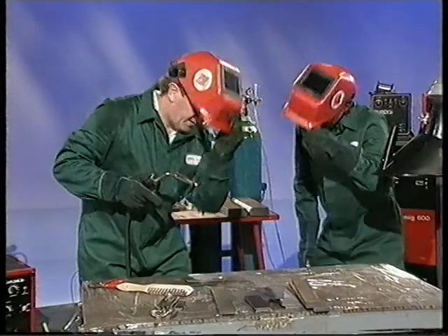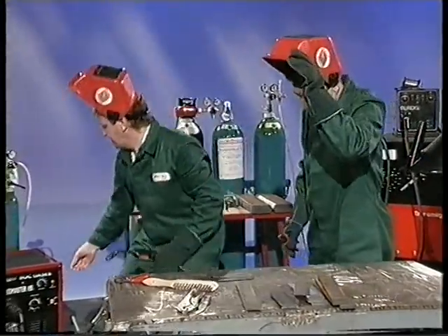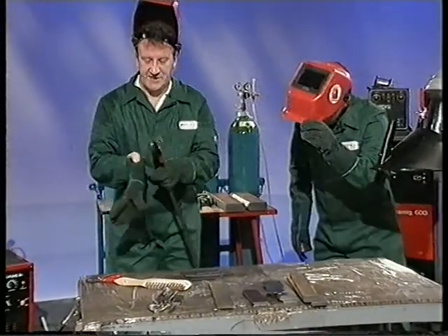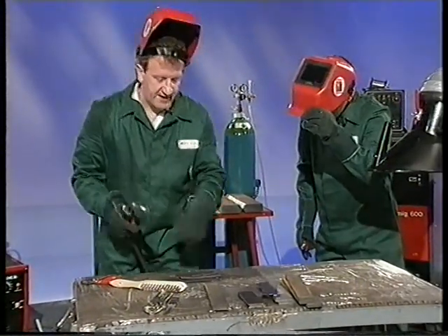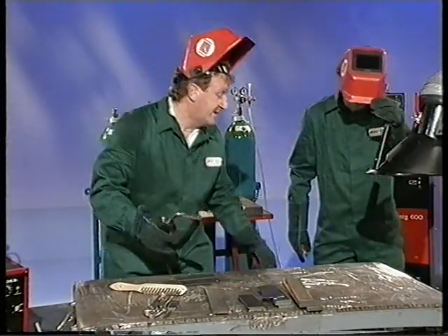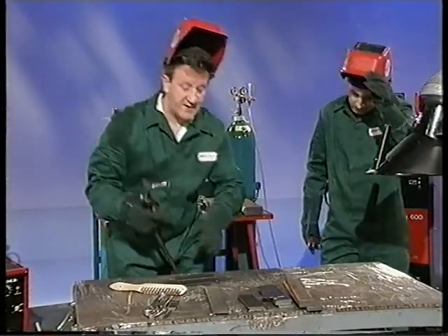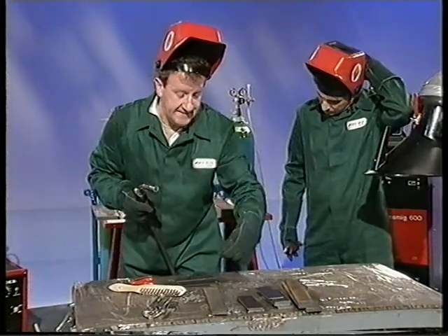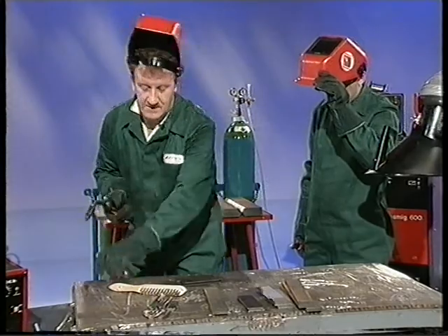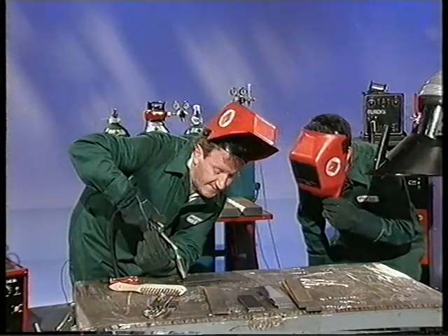Again, a subtly different sound, but still looking not too bad. I suggest maybe just a little bit more wire feed speed on that. We should be able to get a good short circuit condition. Just get rid of this hot plate now, because on thin plate it's quite likely that once it overheats you can burn through very readily. And try again, mind your eyes.